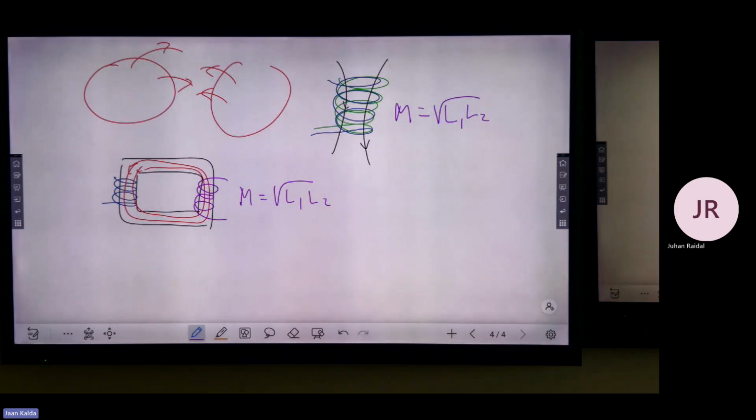So the idea is that if you have your home electricity, and you are connected to the outer network, you have all the fuses so that your current cannot be larger than something. If you short circuit something, the fuses disconnect you, and you will avoid burning things where your short circuit takes place.